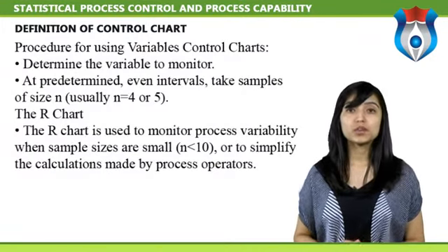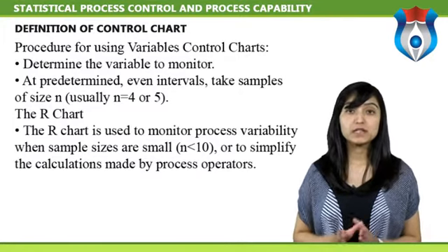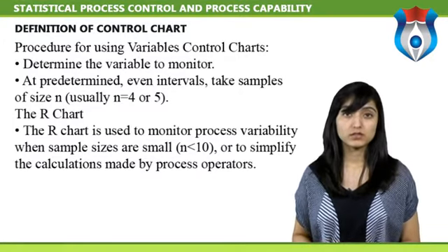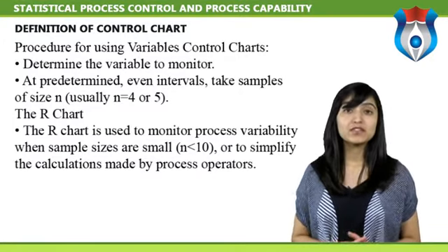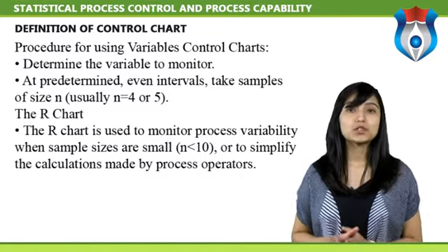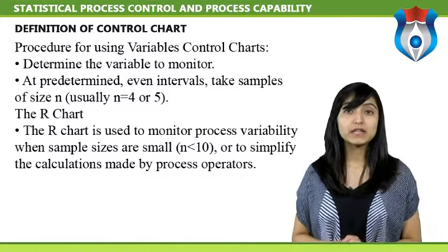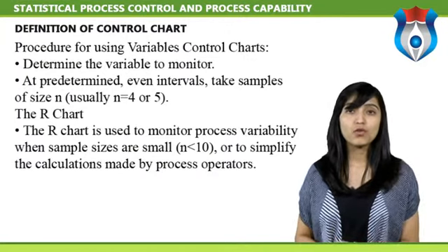Procedure for using variables control charts. Determine the variable to monitor. At predetermined even intervals, take samples of size n. Usually n is equal to 4 or 5.